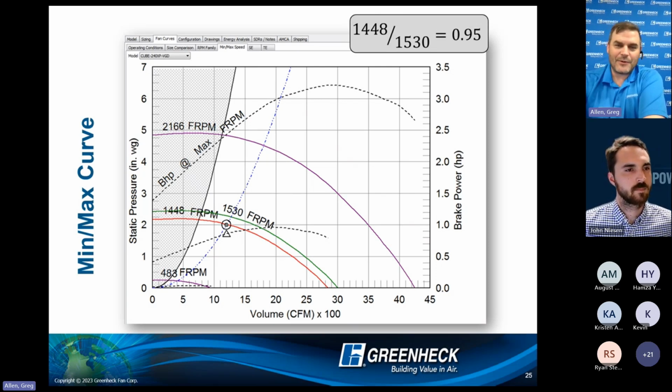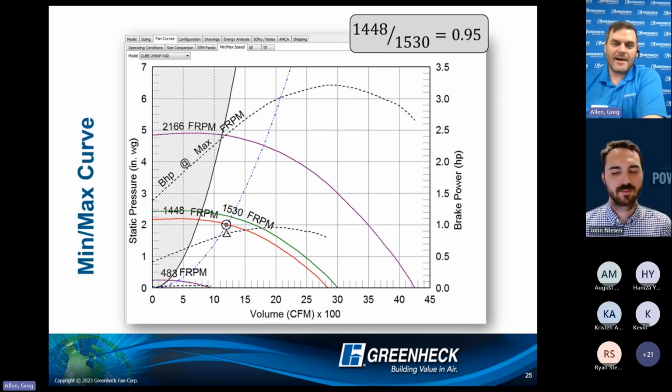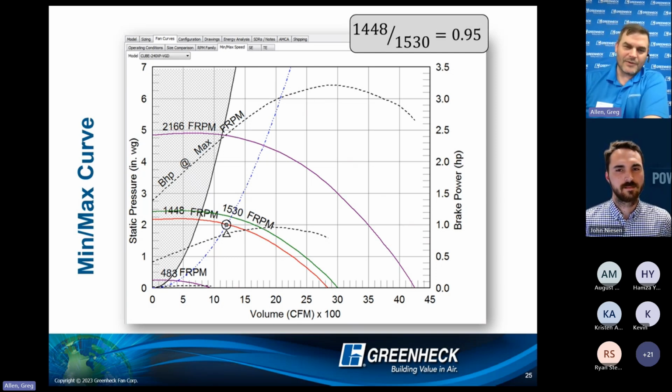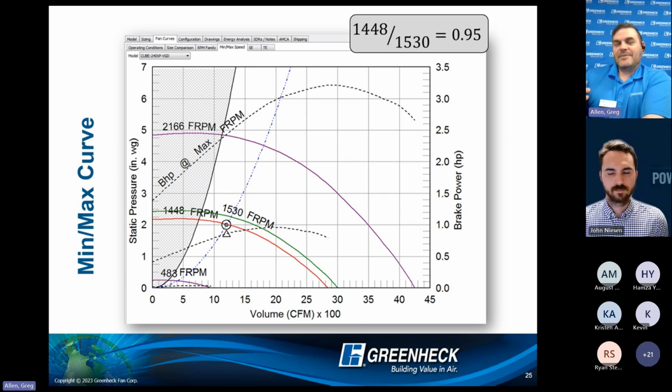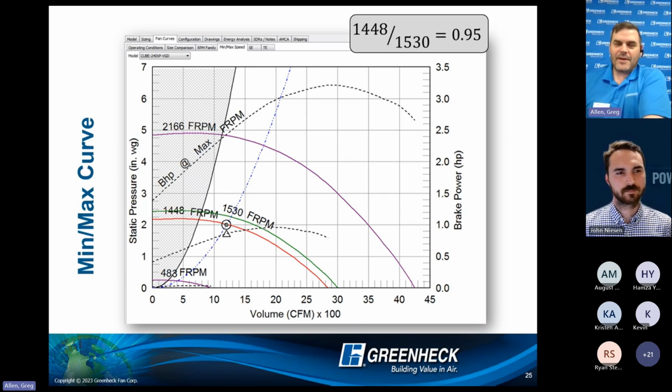I'm not comfortable with that, personally, now mind you, I'm spending your money. But personally, I like picking fans at about 80 to 85%. I like a little more turn-up to overcome system effect, to overcome a couple extra elbows that happen in every project. That's my comfort zone, 80 to 85%. So I would look at this selection and say, not quite.